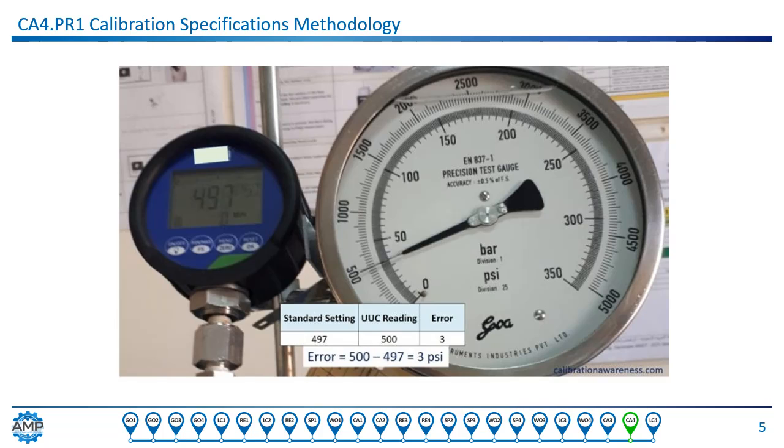It's certainly a best practice to have the calibration procedures conform with a single format for ease of use and consistent data collection. Other things to be considered are whether calibrations will be performed as a loop or individually or in the field or on the bench. These considerations will all be addressed in more detail in function process training later.